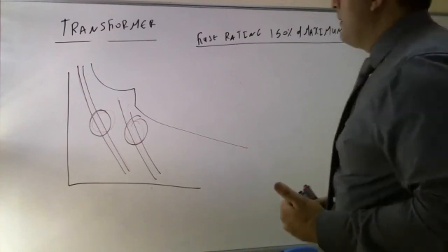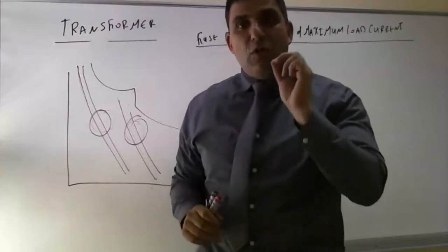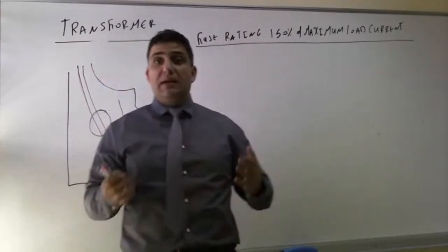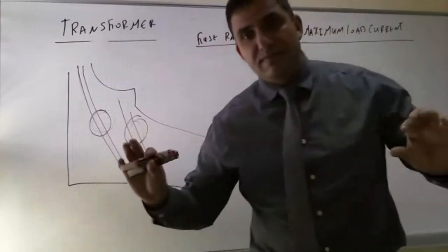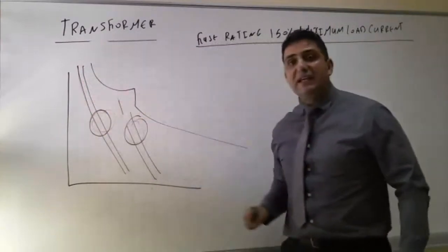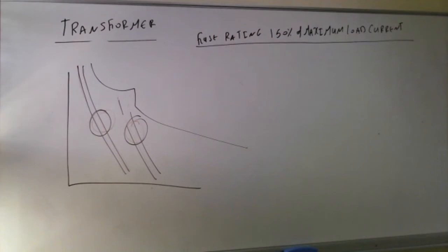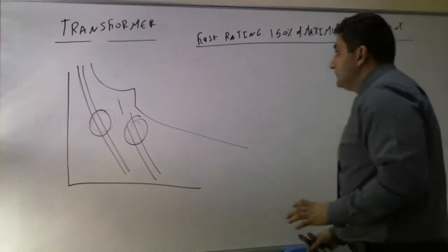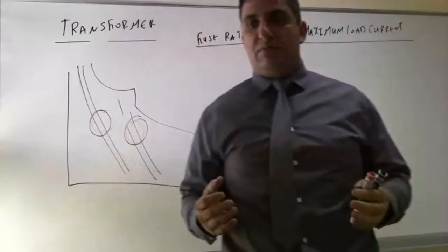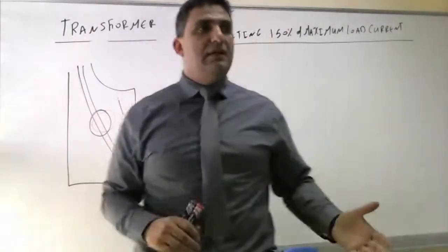So to conclude, to design a fuse for a transformer when the transformer is below 2500 kVA and is not located in a special location, which means I am allowed to use the fuse as protection, I need to make sure the rating of the fuse is within the transformer fault capability. I hope that's very clear to you guys. Do you have any questions? Please prepare all your questions and ask. We need to make sure that we actually comprehend this concept.